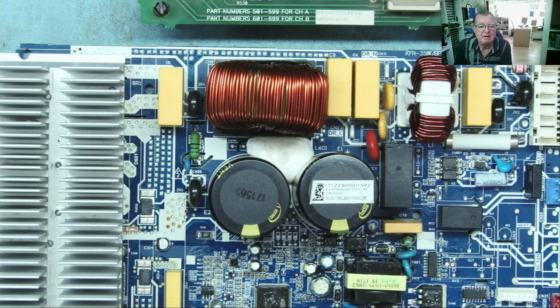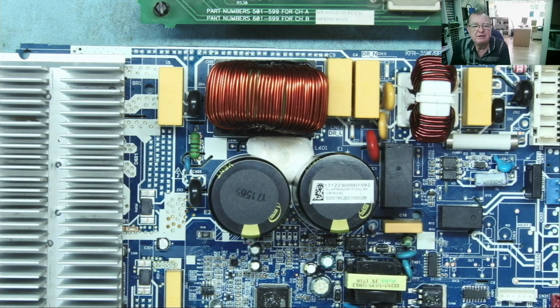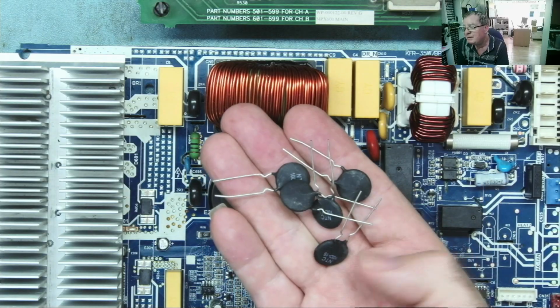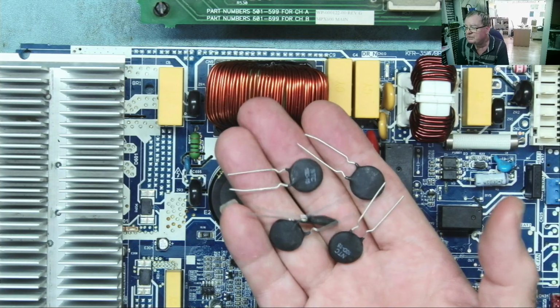On to number 11, varistors or MOVs, thermistors, NTCs, TVS diodes. Okay? The reason I group these together is because they are basically all protection devices. The NTC, and we have some here, but they don't have to be black. They are normally circular like this. It looks a bit like a large black capacitor, but they're not capacitors.